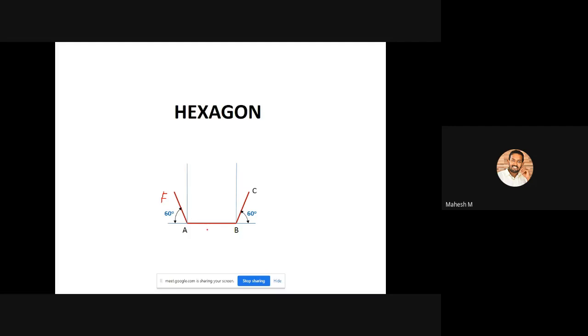After creating the vertical lines from points A and B, you can take your compass with a length of 30 mm. Place the needle of your compass exactly at point F and point C and create 2 arcs like this.